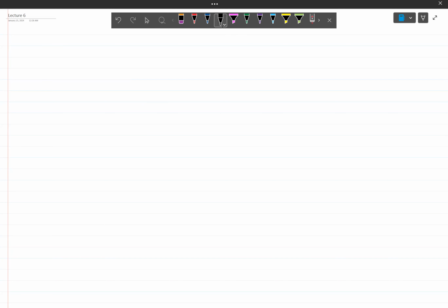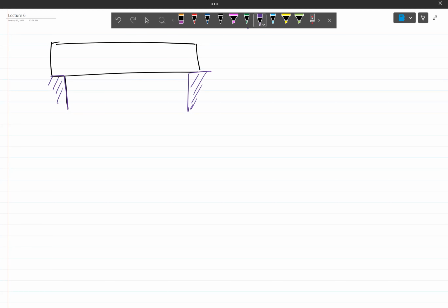So if we have a beam, assuming that these are the columns, okay, so the columns are somewhere here. It typically means that we are looking at the rebars, right? So normally this would be the compression steel. Then here we have the tension. I mean, this is a typical simply supported structure, right?